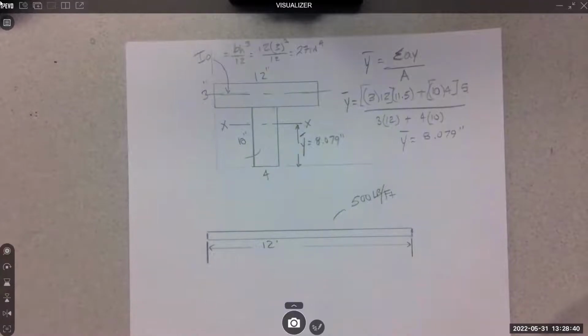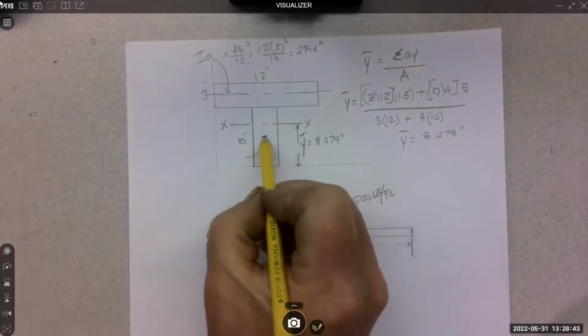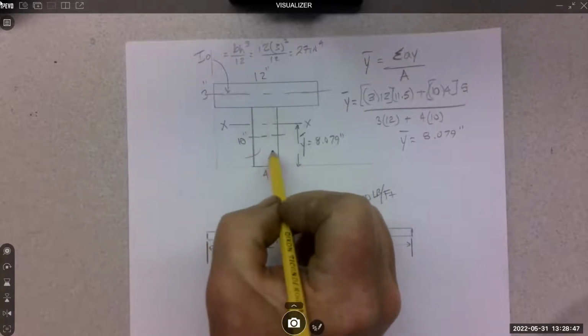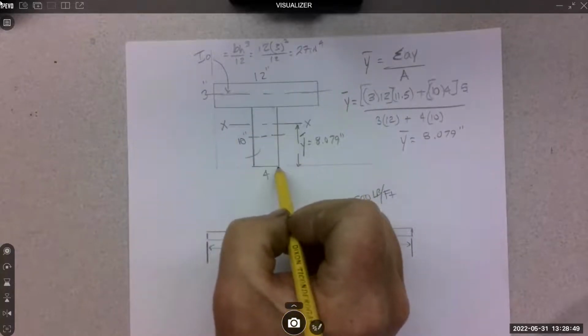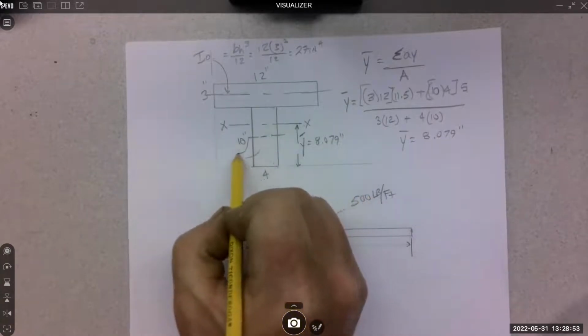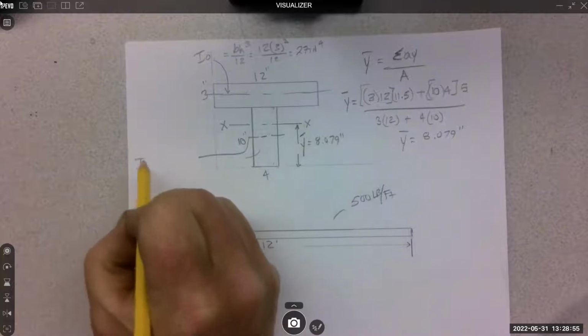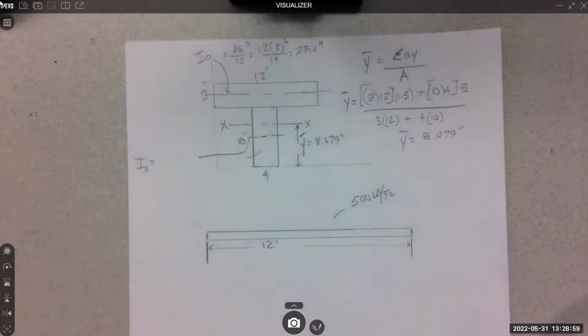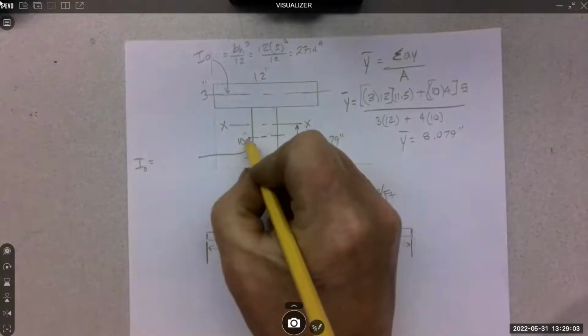And then we have to do the other one. So the other one is here. It's neutral axis of this 10 high by 4 shape is 5 units up, and it's right here. So now we need the I O of that shape. And if I numbered the shape, you'd stick a number to it, but I'm kind of drawing arrows instead.